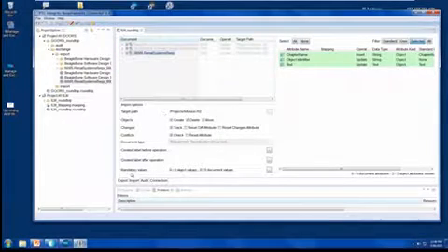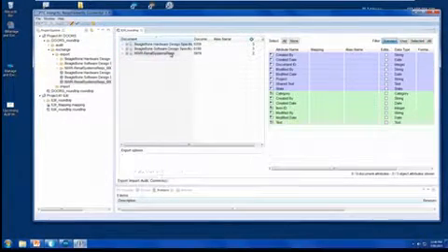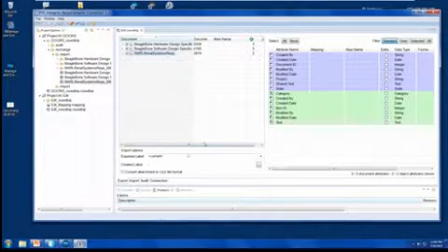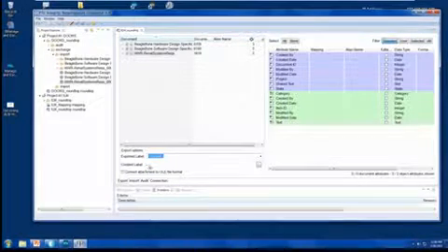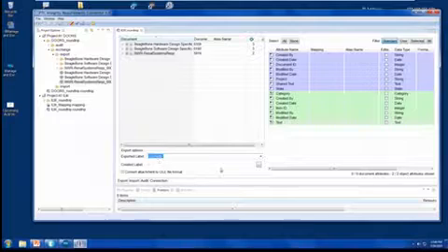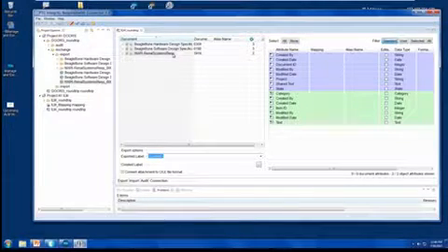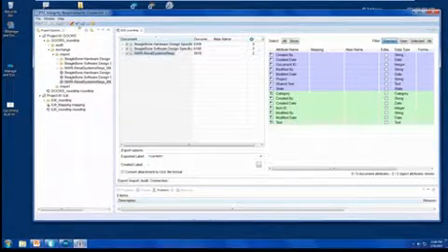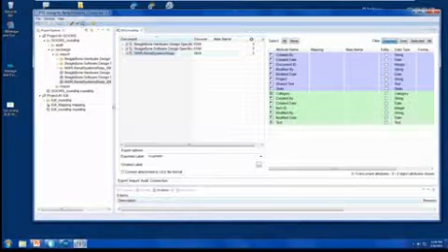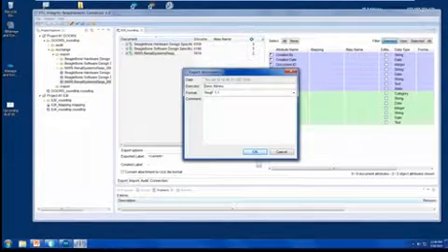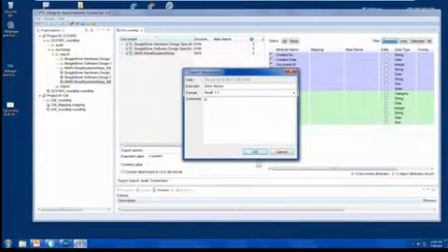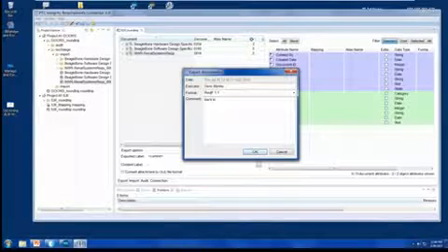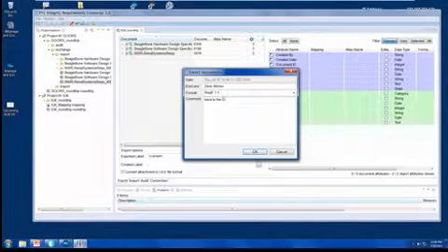So now in IRC, I'm going to export this information. I can export it based on a past baseline if I've got one created, or I can create a baseline after the export is done. I'm going to leave that as is for now, and I'm just going to run my validation and export. It's bundling these things back up, creating that ReqIF blob file, and allowing me to put it where I need to go, back to the system integrator, SI.